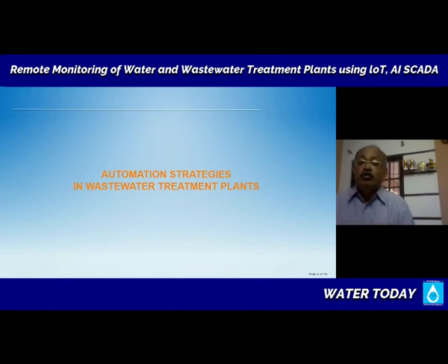So even if you don't want continuous online monitoring, the BOD is something. For example, if you are not having serious BOD issues, many major wastewater treatment plants in the world are operating without online BOD measurement. Then you have the labs which carry out the analysis periodically. Another way is you have these refrigerated sampling units, which every hour collect a sample. I have done systems where these samplers are kept and they collect a sample and keep it in a refrigerated environment in bottles. Then at the beginning of the day, you can take these bottles away, and these samples are with a label, 9 o'clock, 10 o'clock, 11 o'clock, or whatever frequency you are setting. And then you can take these away and analyze in a lab.